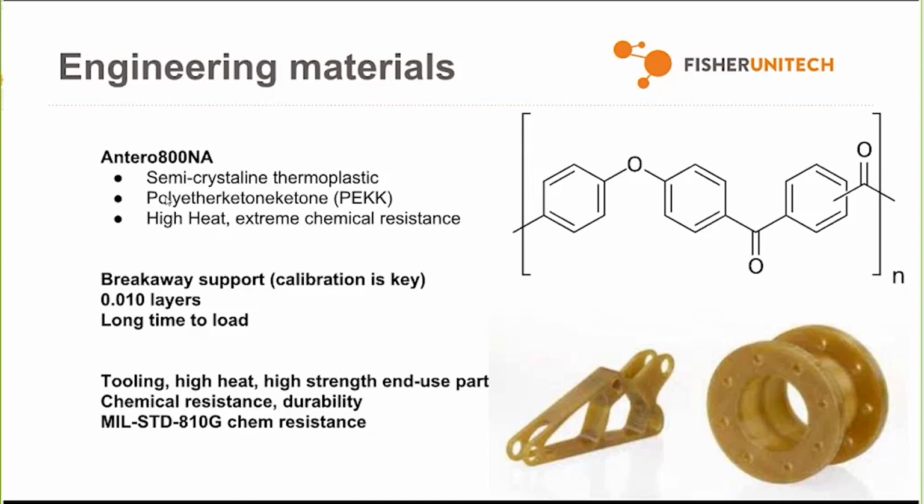It's expensive, but if you're using PEKK, it's because it's the only material that'll do what you need it to. And that's really why Stratasys developed this material. Antero 800 NA refers to the fact that it's got nothing else in it. But coming down the pipe, there will be other materials, or other types of Antero, which include maybe fiber fill or ESD 7 or ESD certifications.